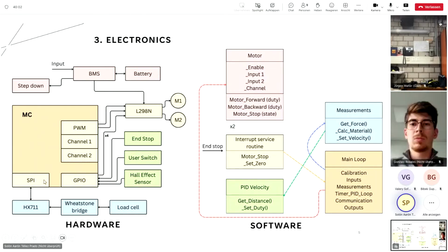through communication. To obtain the applied force, it is necessary to have previously executed a calibration algorithm. This only needs to be done once during the programming of the device to know the conversion values of the force cells.